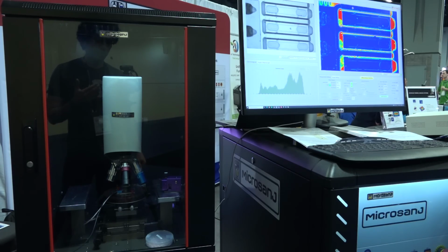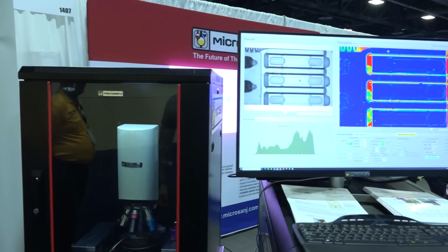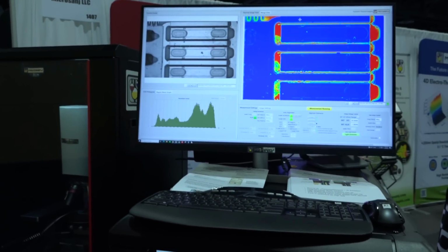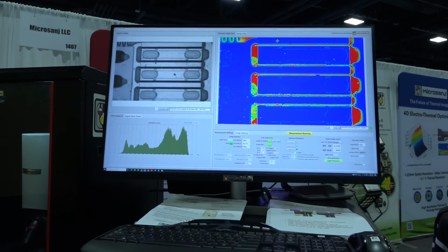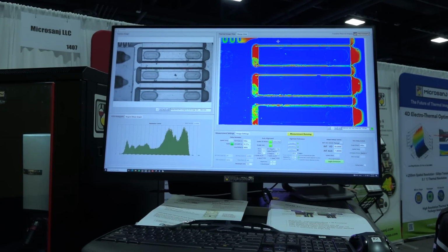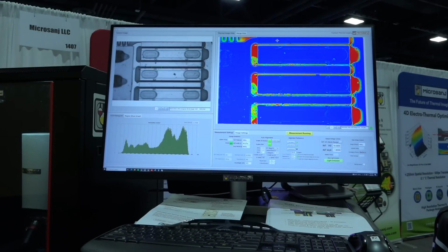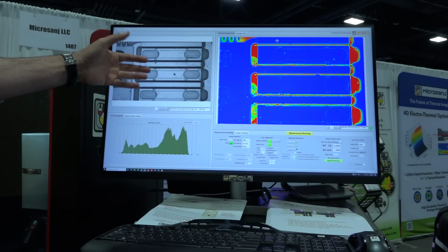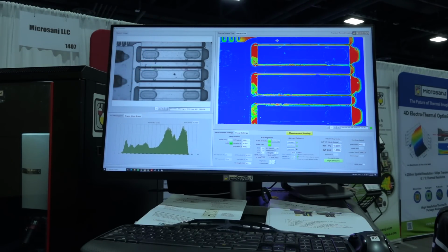So now you're down to 250 nanometer resolution, 500 picosecond timing. So this has some interesting implications on making semiconductor measurements, because now you can look at a gallium nitride amplifier, you can turn it on and off really rapidly, you can put a modulation signal through it, and you look at the thermal flow during the active measurement, which is not something you can do typically. But at the same time, you can see it directly on the camera as well. So the physics of this is a whole other thing, and I think we should cover that on the channel separately, but the ability to make these measurements at this speed is a very important aspect of this entire system.